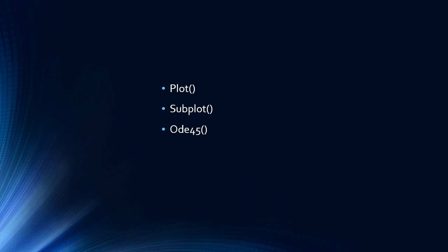In today's example, we will use three very important MATLAB tools. Plot allows us to visualize data. Subplot allows multiple graphs in the same figure. And ODE45 is one of MATLAB's most popular numerical solvers for ordinary differential equations.